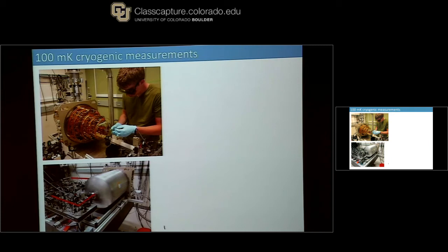Whether I can practically operate this not at cryogenic temperatures: what we use for all this electromechanical coupling is actually superconducting thin films, and those need to superconduct in order to operate. And I could make bulk microwave cavities, but then I worry about what the coupling actually is and how big it is. So practically these things only work cold, though we've operated them at 4 Kelvin with a niobium thin film. Yeah. Or is that what you're asking?